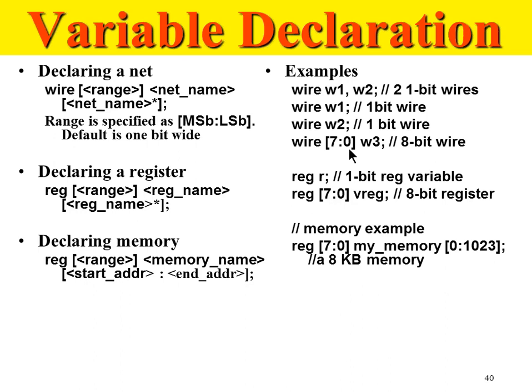See, for microprocessors, typically for microprocessors or even microcontrollers, we have two types of systems. If you recall, it's called a little endian system and a big endian system. What we represent here is a little endian system. It means on the right hand side is the LSB value, and the left hand side is the MSB value. That is how a little endian system goes. If I would have said 0 to 7, it's also 8 bits, but rather than 7 down to 0, if I say 0 to 7, it's a big endian system.